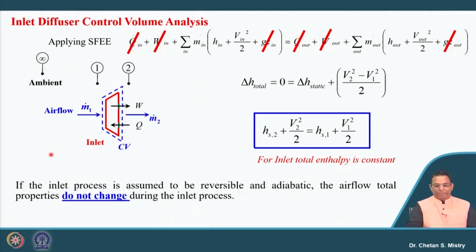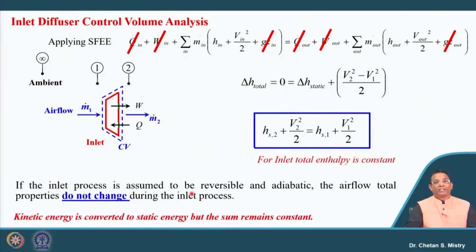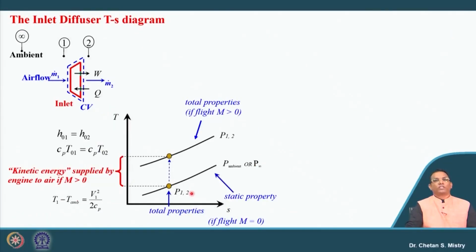So, the inlet is a process where we can assume it to be reversible and adiabatic, in which my total properties are not changing. The kinetic energy is converted into static energy, but their summation remains constant. We need to understand this part, this is very important.